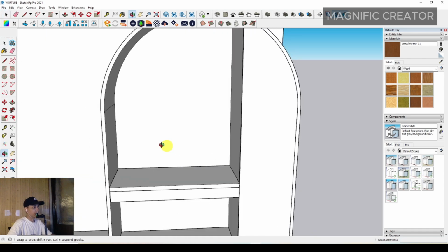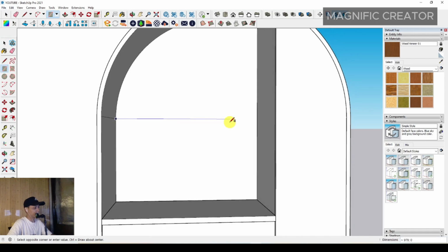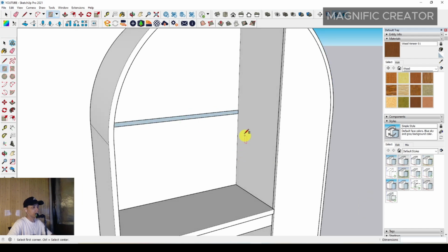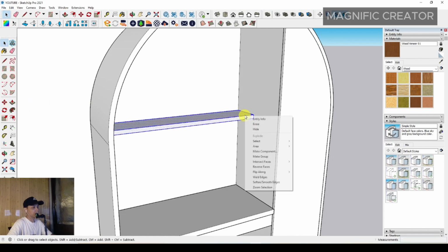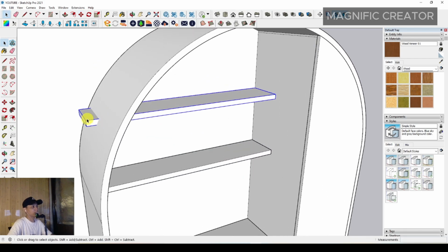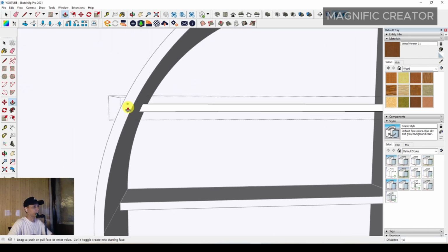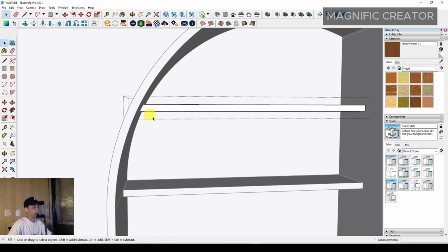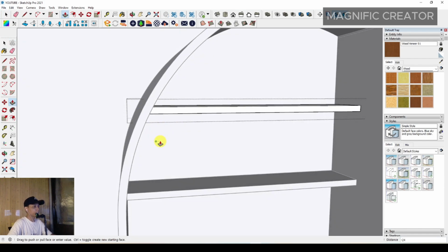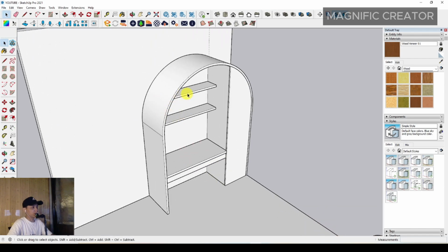Okay, and after that we can make an additional shelf over there. You can make an additional shelf to make the space more functional. Just make it a group and move it up. Then you can adjust the extension of this object, then select push and offset to the position. Okay, push the position, sorry.